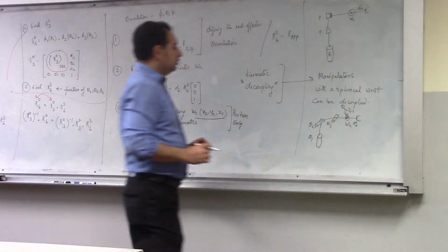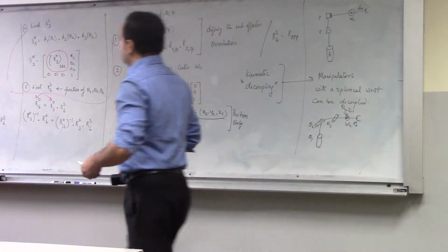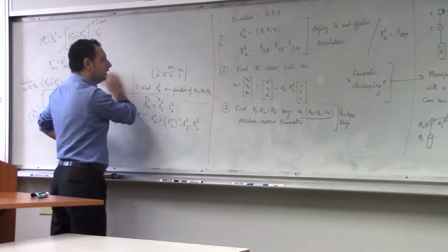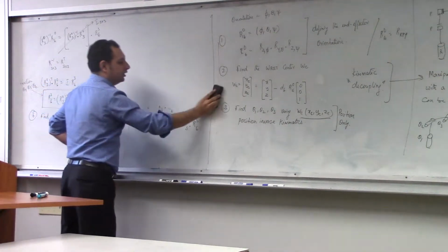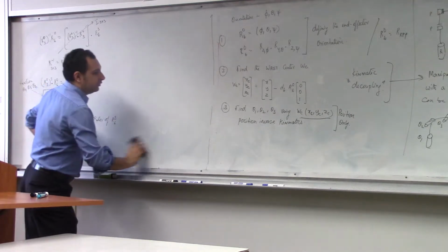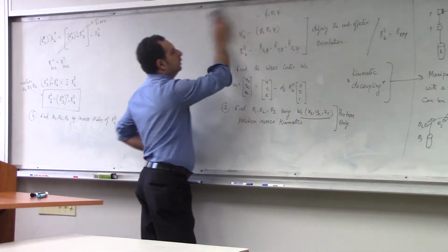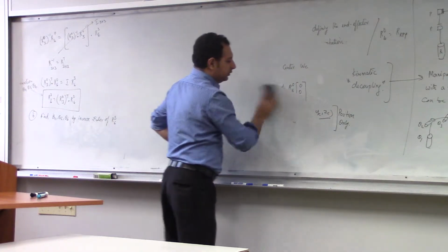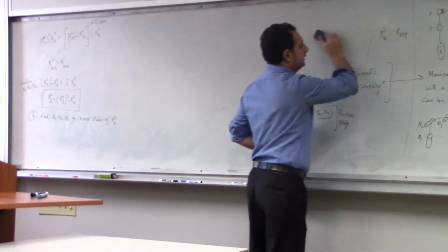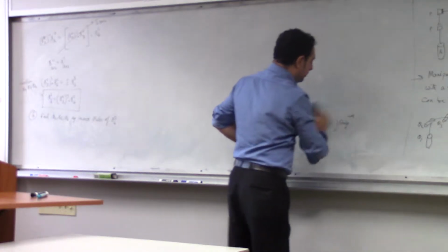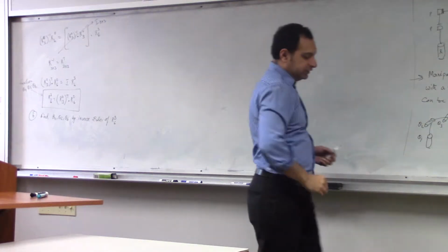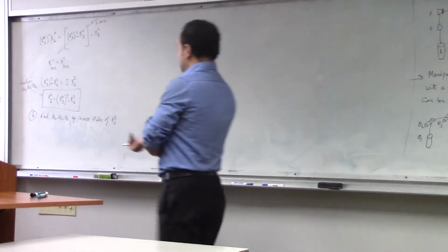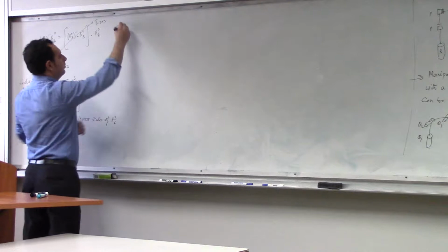Complete idea of how to do inverse kinematics for a 6 degree of freedom manipulator, because most of the 2 or 3 degrees of freedom do not control the orientation, they only control the position of the manipulator. Okay, I'm going to email you the exact lab case where we'll have a DH table. I think you will work it out before you come to class so we can check the solutions that you have derived by a MATLAB simulation.